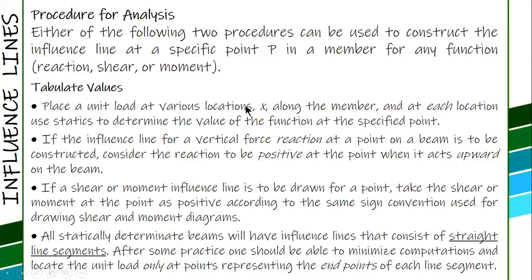So every time the unit load moves, use statics, meaning to say, use the conditions of equilibrium, either summation of moment or summation of force, to determine the value of the function at the specified point. The function is either reaction, shear, or moment. That will be discussed in the sample problem.